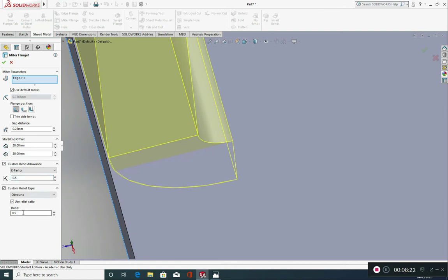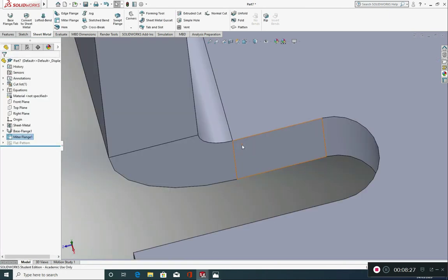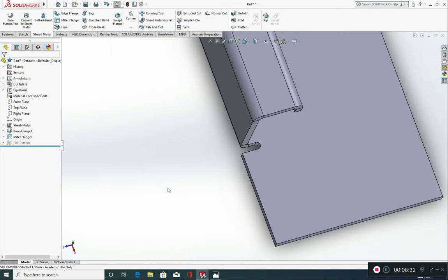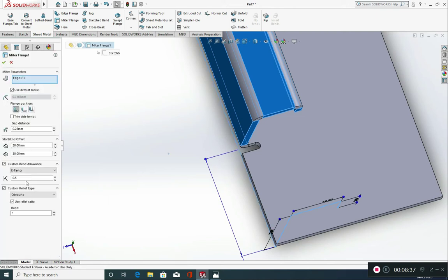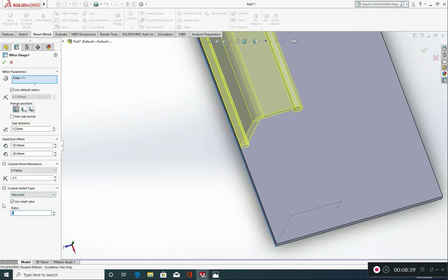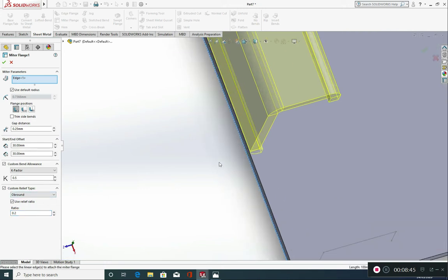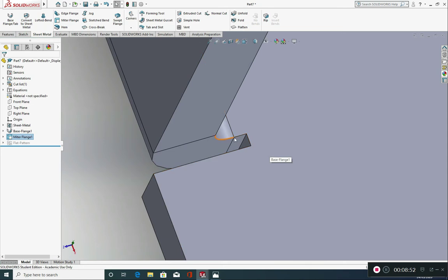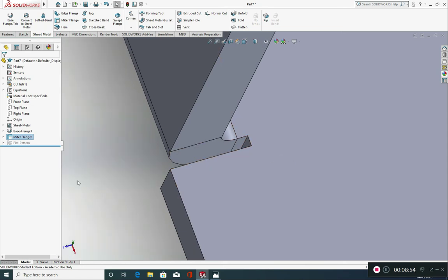Into this one, custom relief type. Let's put it in at 1 now, so you can really see a difference. Green tick. And you can see the increase happening there. So back to edit feature. Let's go back to here and type in 0.2. However, this time let's go into rectangular and green tick. So you can see now that the relief type is different. It's taken on a more rectangular form.